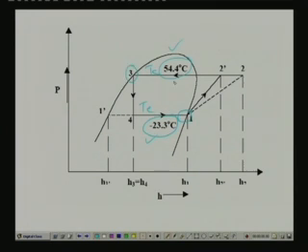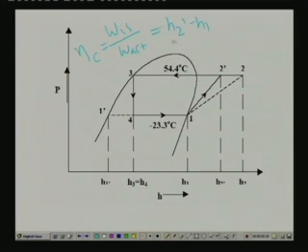So, this is the information given to us, and it is also mentioned that the isentropic efficiency of the compressor is 0.65. What do you mean by isentropic efficiency of the compressor 0.65? That means the actual compression process 1 to 2 is non-isentropic, whereas 1 to 2 dash is isentropic. And from the definition of isentropic efficiency of the compressor, you can write the isentropic efficiency as isentropic work input divided by the actual work input. So, from energy balance, this is nothing but H2 dash minus H1 divided by H2 minus H1. This is given to be 0.65.